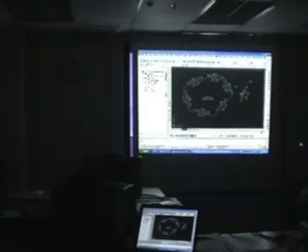Right, so whether you want to use dynamic labels or static labels, it's completely up to you. Some people like to use dynamic labels because at least they know, okay, if I make any adjustments, the labels are automatically updated with the line. Some people want to use static in case they say, what if I accidentally move the line and I don't realize it? Because when you move the line, the dynamic labels follow the new position, right?